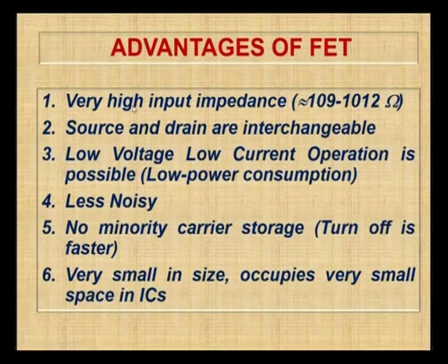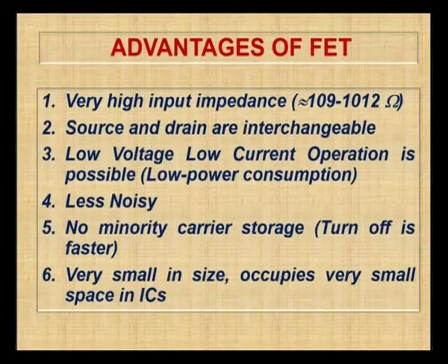We can also make the low input impedance of a BJT high by designing properly, but as the complexity of design increases, this also leads to design complexity. So, we need to go for another device which has high input impedance, where we are not going to use a bipolar junction transistor.